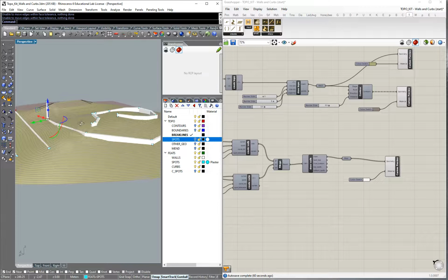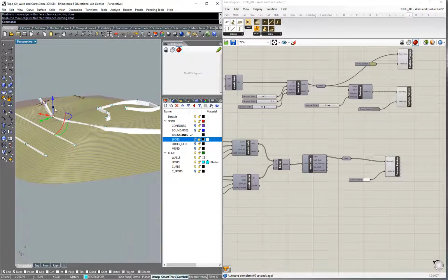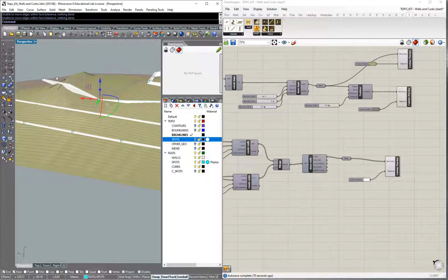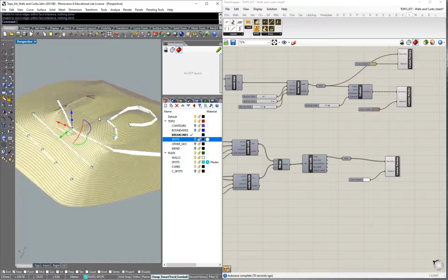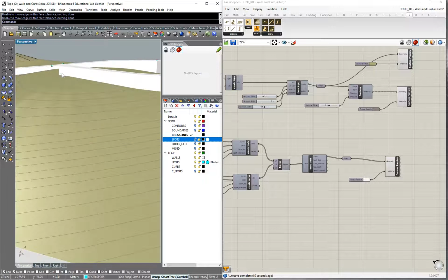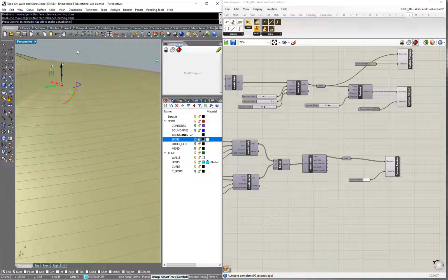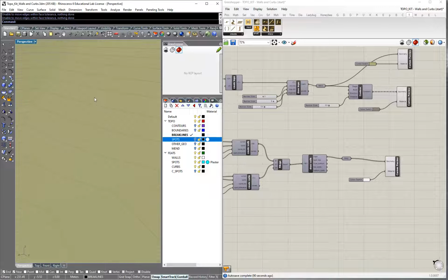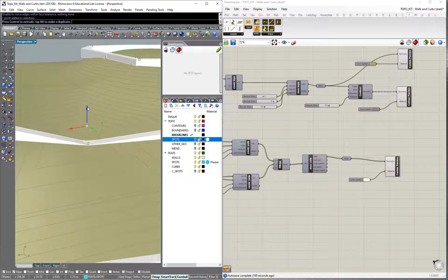So with this option, you can change also the heights of the wall along the whole curve or polyline. And you can have walls with different heights. So it's super useful when you are a landscape architect and you want to generate different sort of heights and walls all following different curvatures, or for example a spiral wall that goes up like this one, and you want to have different heights for your points. You will see here the wall behaves quite well. Now the wall here in this very moment hasn't interacted with the topography yet, as well as the curves.